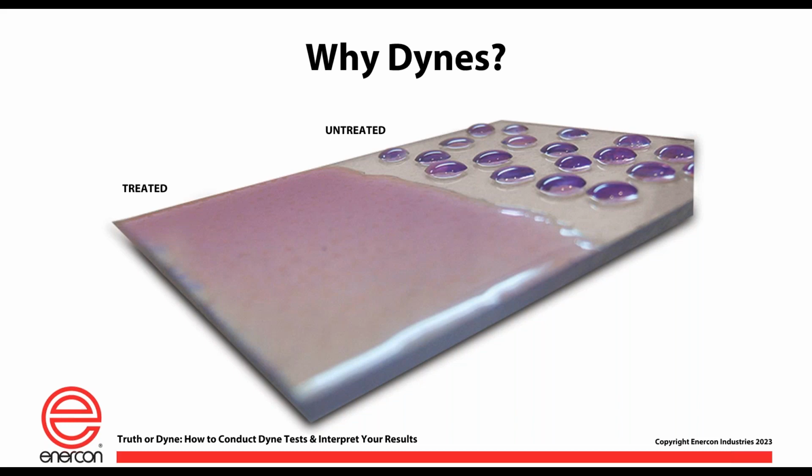And in one case, at the same power, the polyester film is going to get a much higher dyne number, let's say 50 dynes, wherein the polypropylene might only get 40 dynes. And we're using the same treater, same speed, same power, same everything. So the point of this is dyne numbers will vary with the capability. So just having a blanket target and saying, hey, every film we treat has got to be some big dyne number, just doesn't make any sense in relationship to how the films actually respond to surface treatment.